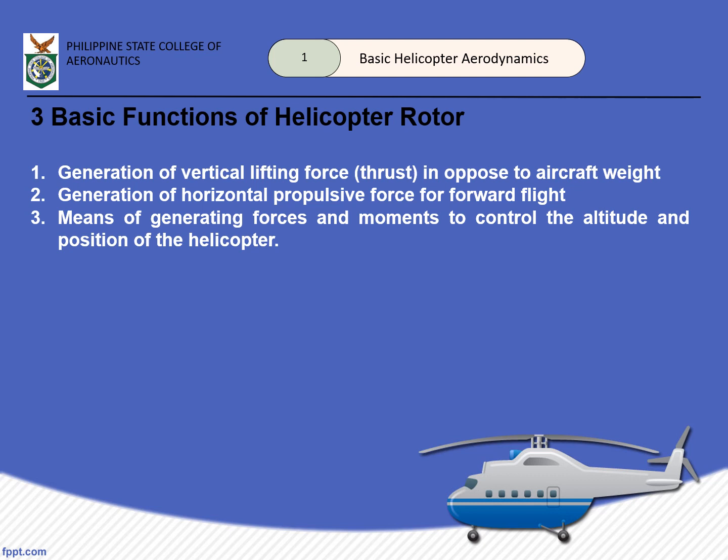Pretty much the same essence as fixed wing, but unlike a fixed wing aircraft where certain roles are divided, all three of these must be supported by the helicopter rotor alone. So, ganun siya kahalaga. In order for us to ensure that the rotor can perform these functions, the rotor designer needs to have significant knowledge both of the aerodynamic environment in which our rotor will work and how the aerodynamic loads could influence the dynamic response of the blade and the overall rotor behavior.